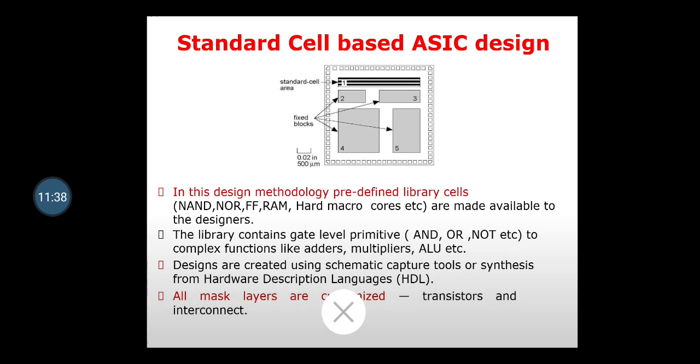Now the next ASIC is the standard cell based ASIC design. In this design methodology, predefined library cells, that is NAND, NOR, flip-flop, RAM, etc. are made available to the designers.